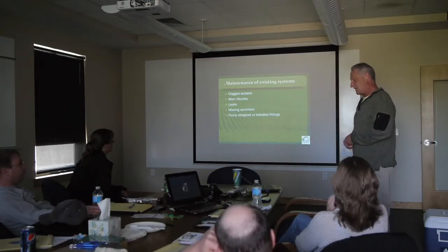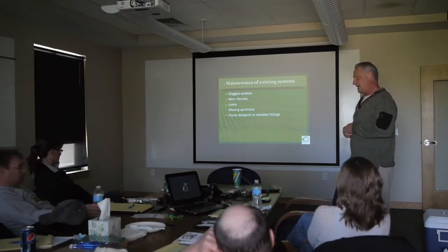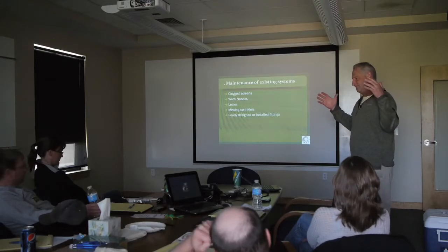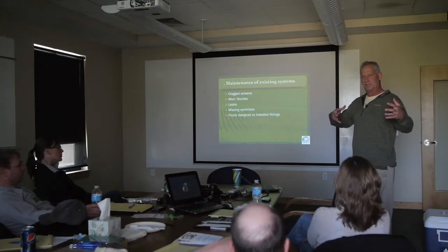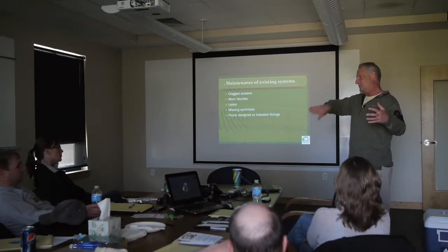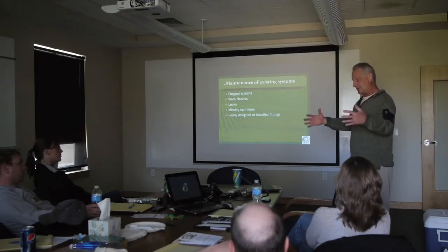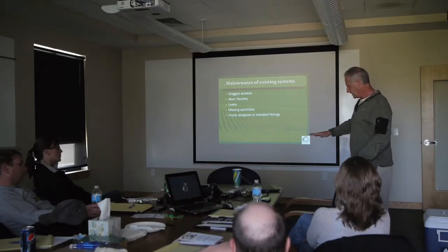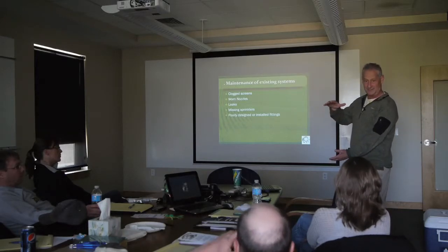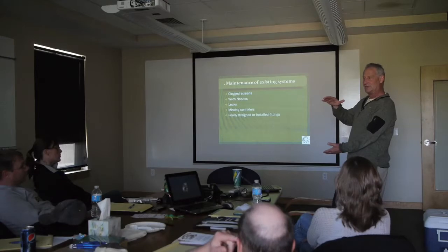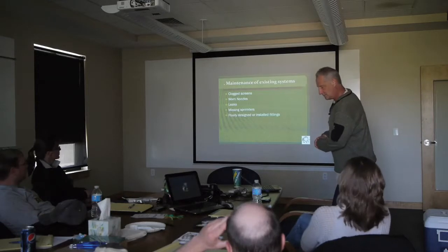Maintenance is really critical. Look for clogged screens. They'll have the intake, and sometimes these things will be clogged up. Sometimes they'll put a sprinkler in the pickup, and the sprinkler will keep debris out of the screen. Sometimes the screens will get plugged up, and so you'll see that the water in the ditch might be a foot higher than the water where the pump intake is. Okay, that's a foot. You don't want that foot of loss, especially on the suction side. So be careful of that.